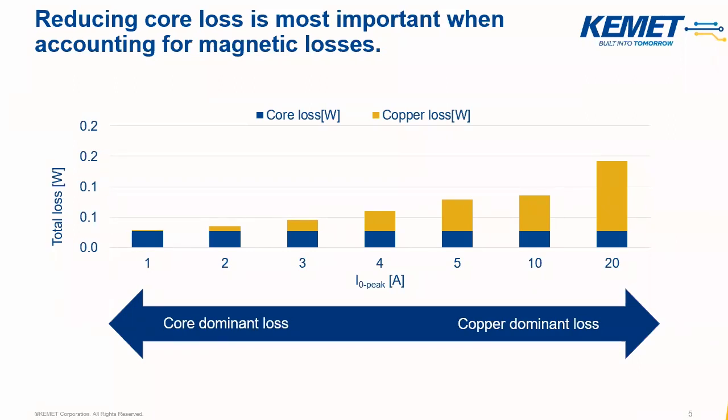Yeah, that's a good point, Alex. So it sounds like you can almost compound these two things together. You go smaller and smaller, or higher in frequency, in an attempt to make the inductor smaller, but you start to experience more loss in the core material itself. And on top of that, Alex, you also start to experience more copper loss, because your wires are getting thinner, right? Right, yes.